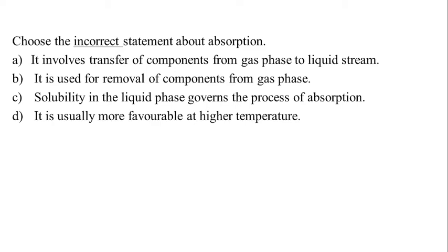In fact, it forms carbonic acid. If you have this, you can very easily dissolve this CO2 by lowering the pressure or heating this particular CO2 loaded water, and regenerate the water and reuse it. The same thing is true in case of monoethanolamine and diethanolamine. The H2S forms a weak chemical bond with the solvent, which is in the aqueous phase. It is absorbed in the absorber, and in the regenerator, it is practically boiled off. It's stripped off, or you can say that it's distilled off.